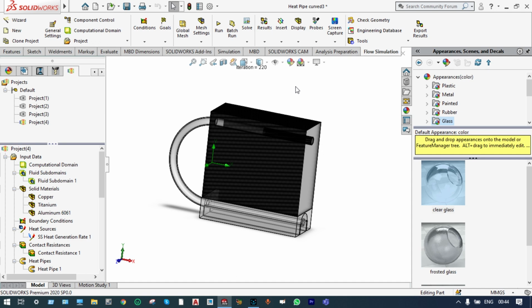In that case, we could see that the temperature in the evaporator, condenser and the adiabatic zone had very little temperature increase, and the temperatures in different zones differed by 1 degree centigrade. That means it was having temperatures of 32, 31 and 30 degrees centigrade when we forced air from the backside at a velocity of 30 meters per second.